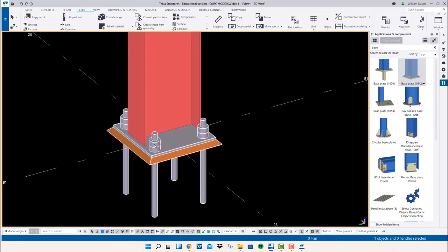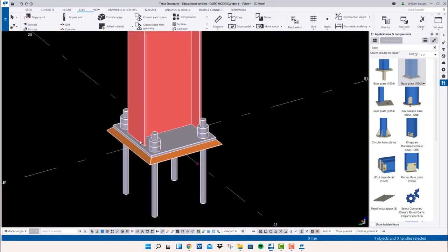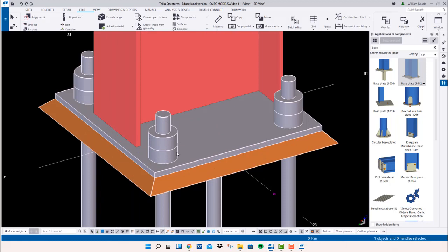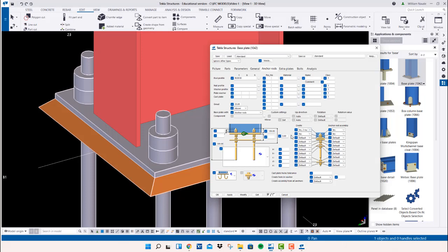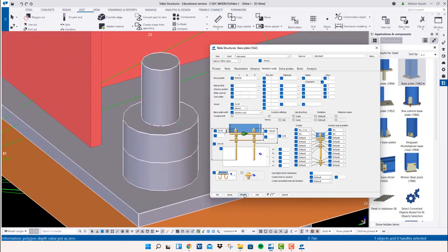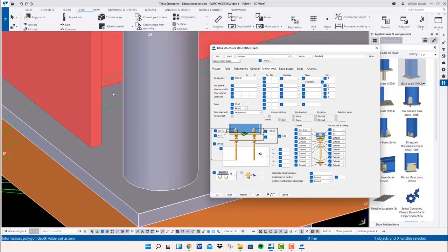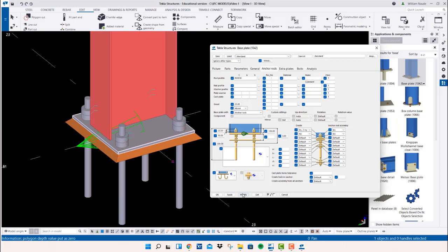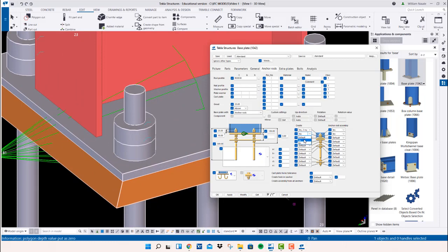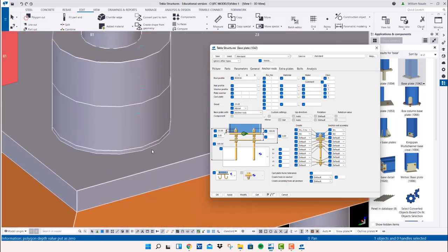Now, if you want to use this, but you want to manipulate a few things, for instance, these nuts are just too big. Now, the problem is, if you go to our anchor rods, it doesn't really always provide you with everything you need. But let's say, okay, this one will be, let's say 25, and you'll see that your nuts just decrease in height, as you can see. So you can actually do it over here. Oh, that was just too much. Just 25, please. Okay. So now the nut, if I go with this, the washer, there's a 2 millimeter, and there's your 2 millimeter washer.